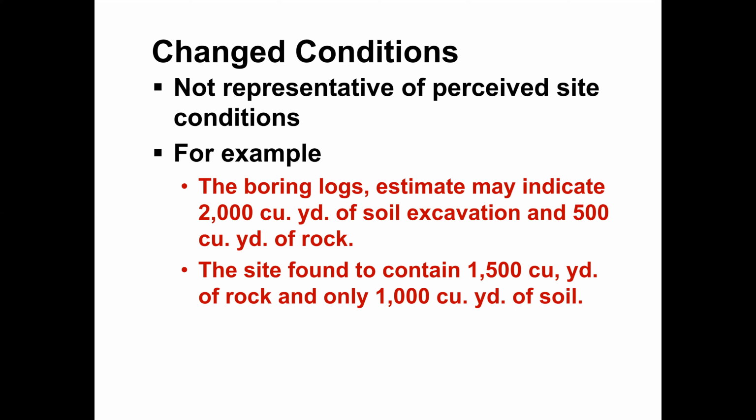So that shows the strata underneath the soil. Sometimes the soil strata is not the same as given in the soil investigation report or in the boring log. Okay. So then we say it's a changed condition. Now they are going to give an example here.